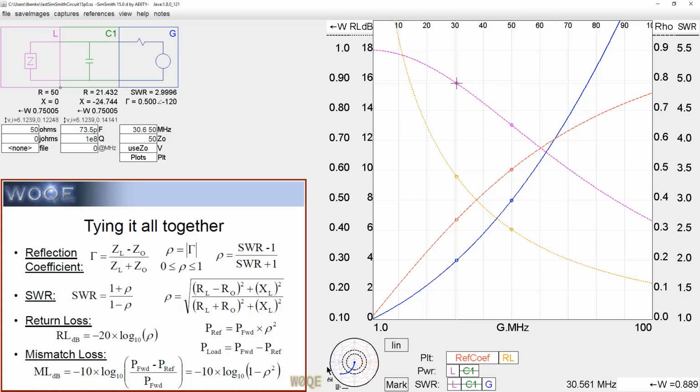Well, I just said a minute ago with a reflection coefficient of 1/3 coming back, reflection coefficient 1/3 right there coming back, that's 1/9 the power. So we have 1 watt minus 1/9 of a watt. And what do we get? 8/9 of a watt, 0.889. Pretty cool. And in the case of 3-to-1 SWR here, the 3-to-1 SWR has a reflection coefficient of 0.5.